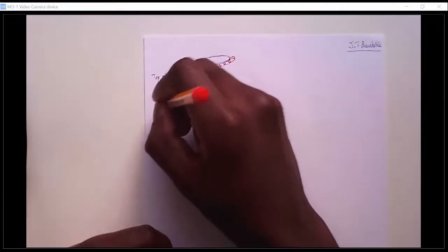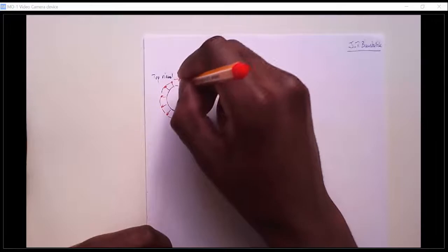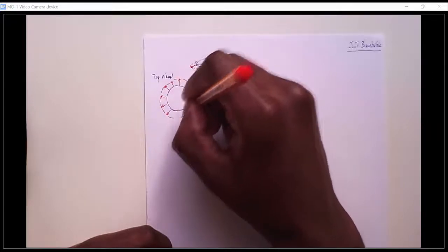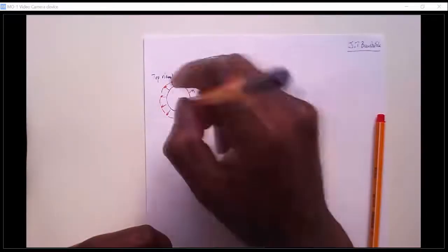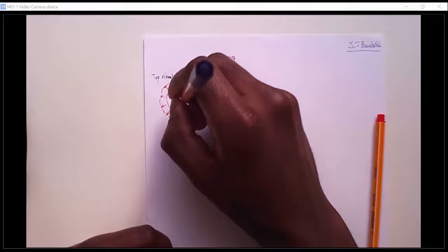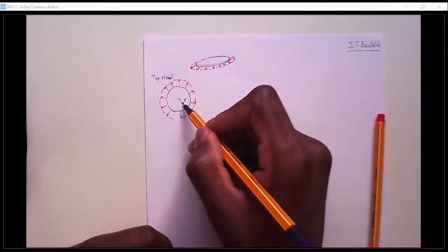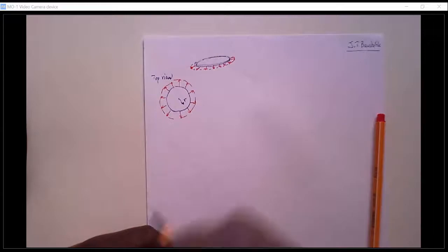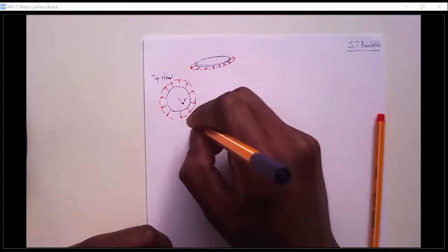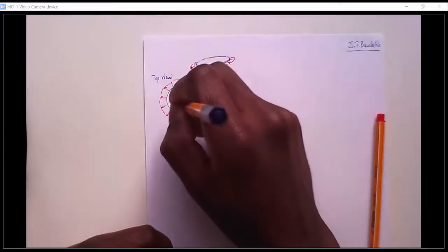And what we want is to figure out what are the stresses, the normal stresses in the radial direction. So basically, if we define a center here for this disk, what are the stresses in the radial direction, and the stresses perpendicular to this radial direction, that would be a direction phi. I can't really draw it here, but it will be 90 degrees to the r direction. So if we draw like an infinitesimal element of this disk, let's say some element that's here,